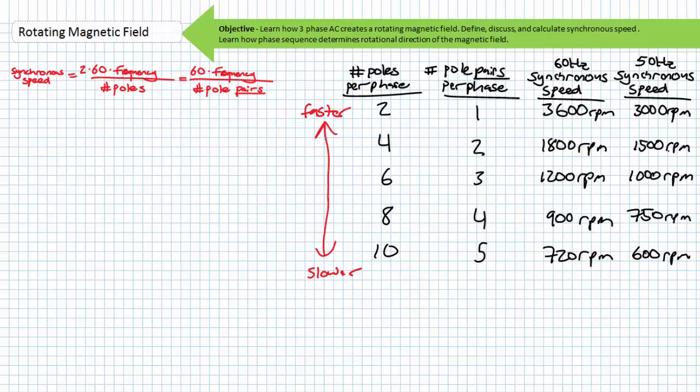If you want the motor to spin fast, connect fewer pole pairs per phase. If you want to decrease speed, connect more pole pairs per phase. Such large quantum jumps between predetermined speeds, however, aren't exactly the smoothest means of speed control. It is for this reason that multi-speed motors have largely become a thing of the past and are being replaced by motor drives that keep the number of pole pairs fixed and increase or decrease the supplied frequency.